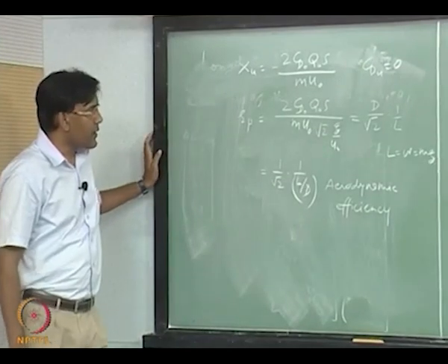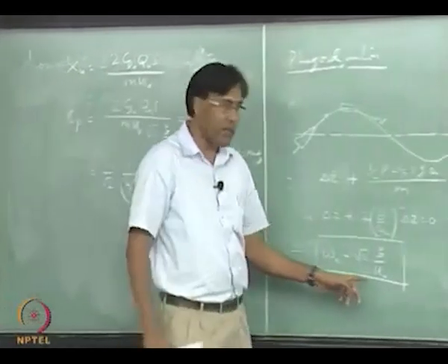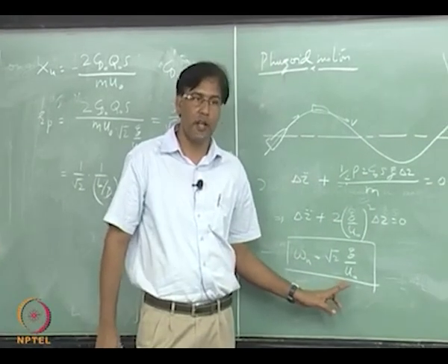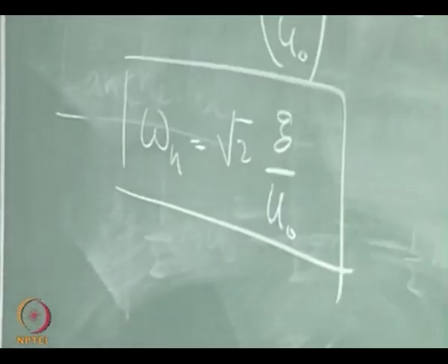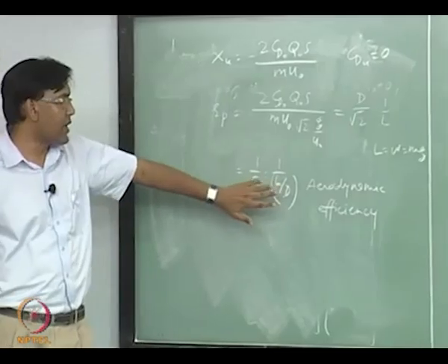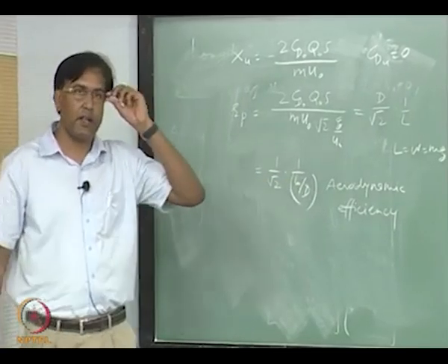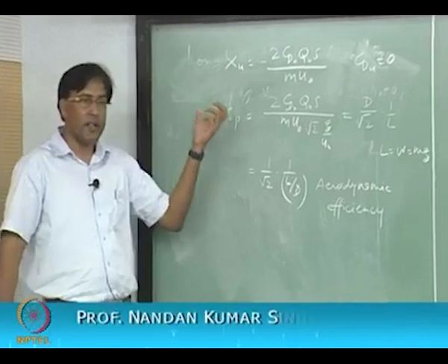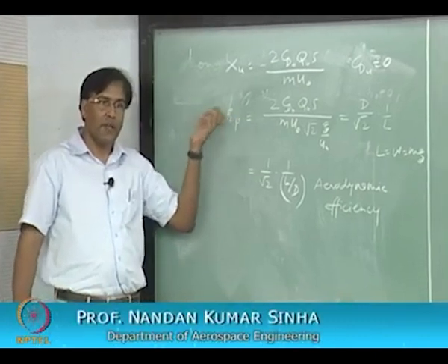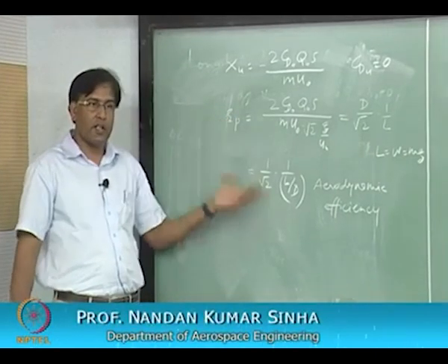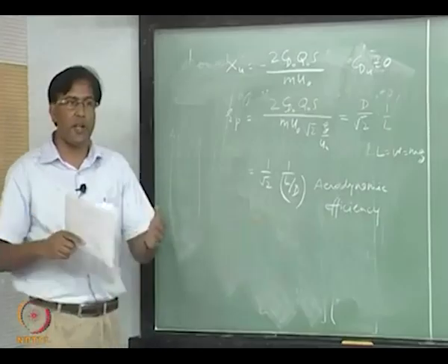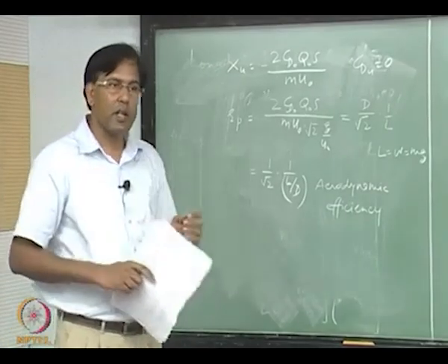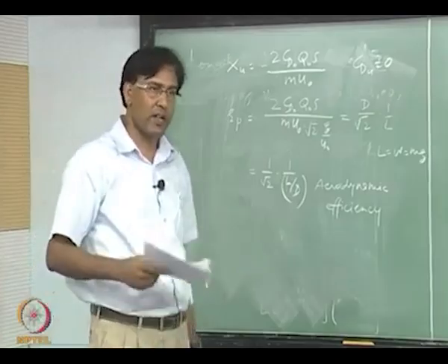right. The frequency is inversely proportional to the trim speed, right. So, let us say you would still want to keep this L by D high. So, what we get is this zeta of P, damping ratio in Phugoid, goes down, and let us say it is not meeting the requirement, okay.